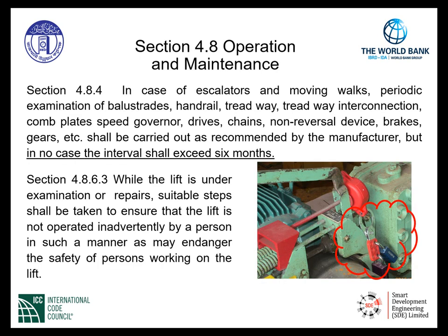Section 4.8.4, in case of escalators and moving walks, periodic examination of balustrades, handrail, treadway, treadway interconnection, comb plate, speed governor, drives, chains, non-reversal device, brakes, gears, etc., shall be carried out as recommended by the manufacturer. But in no case shall the interval exceed 6 months. This is the same type of requirement that was given to us regarding lifts as well. Again, notice the interval shall not exceed 6 months.